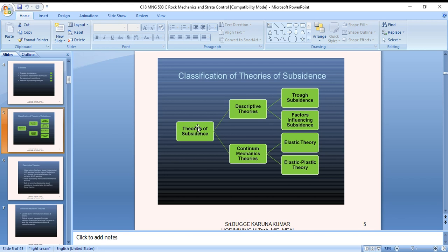The first manifestations of subsidence may be a convergence or succession of local failures in the rock surrounding the opening, such as repeated sloughing from the immediate roof. This phase of the process is termed subsurface subsidence, as opposed to surface subsidence, which is evidenced by the depression in the overlying surface. Surface subsidence may range from a deformation that is barely measurable with precision surveying instruments to a void having a volume comparable to that of the excavated volume of the opening.